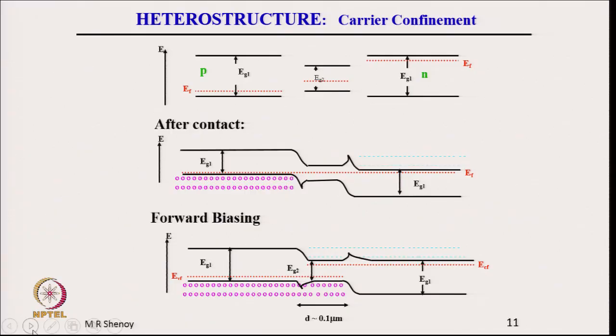All right. So, let me illustrate why double heterostructure and what is carrier confinement. Recall that the double heterostructure comprises a thin layer sandwiched between two layers of another type of semiconductor. So, this is a thin layer sandwiched between two other layers of semiconductor. If this is the x direction, or depth direction, and I rotate this through 90 degrees, then I will have the material like this.